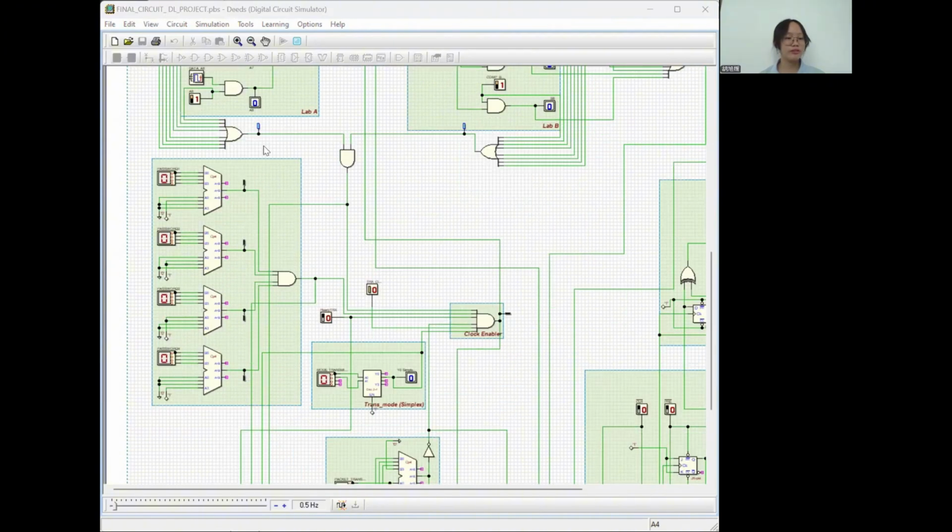For the password comparator function, we use 4 4-bit comparators and 4 input hexadecimal. We set the A0 to A3 values by connecting them to the high level or low level input. We also use the AND gate, so only when all passwords we enter are correct, the circuit will work. When we enter the correct password, which is 2638, the lighting LEDs indicate that we entered the correct password.